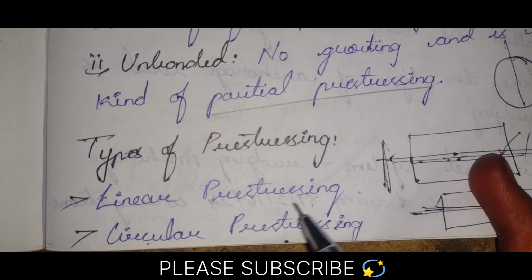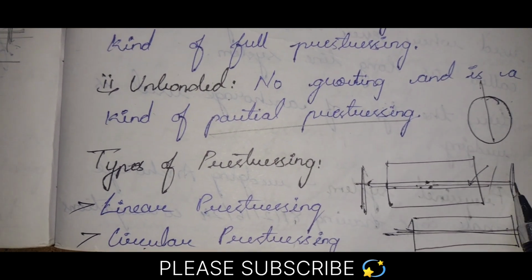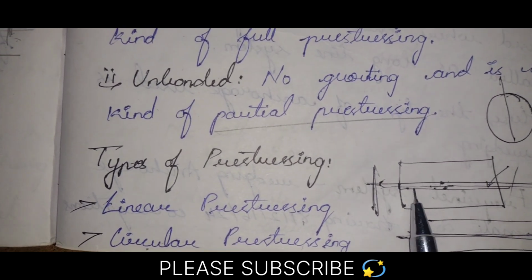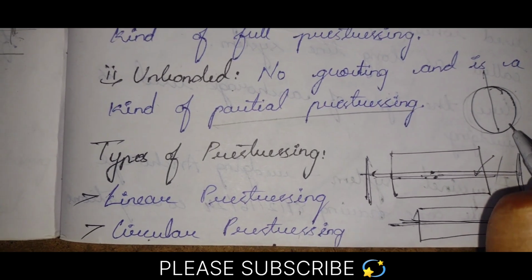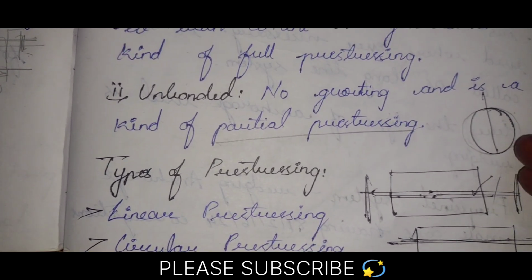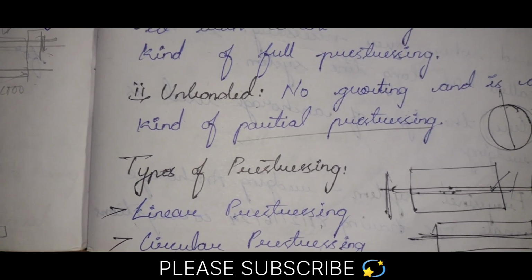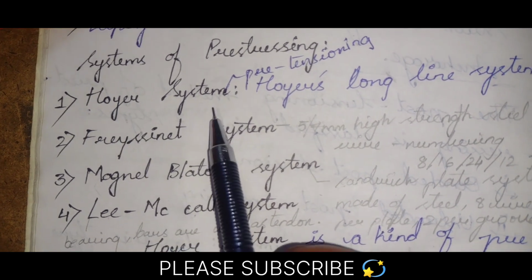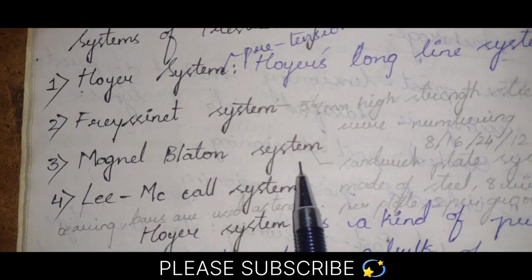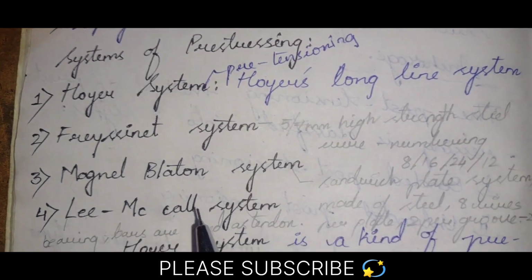Generally pre-stressing has some types: linear pre-stressing and circular pre-stressing. Whenever it is along a single line length, we call it linear pre-stressing, and if it is happening in terms of a circular shape, that explains the type. In the next video we'll see the systems of pre-stressing, like the Hoyer system, Freyssinet system, Magnel-Blaton system, and Lee-McCall system. These are generally the 4 systems of pre-stressing that we use.